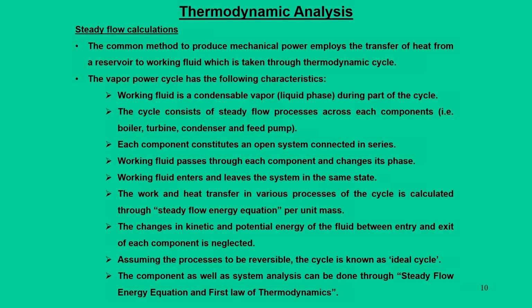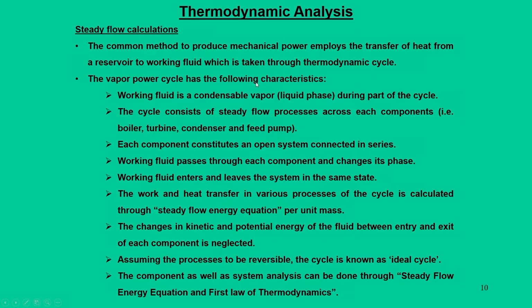Now, moving further, we will talk in more detail about thermodynamic analysis, and this thermodynamic analysis mainly deals with steady flow calculations. We all know that the steady flow energy equation is one of the fundamental equations that was taught in the level 1 thermodynamics course, and we are going to use those steady flow calculations for vapor power systems. If you take a vapor power cycle and try to understand that cycle through the steady flow energy equation, there are certain characteristic features that we can highlight here.